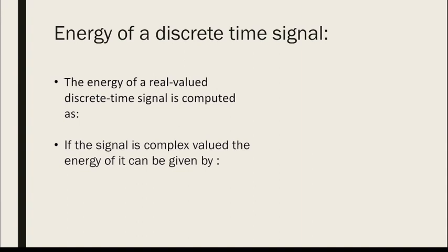Both of these are given by two different equations. For the real value, it's given by Ex equals the summation when n equals negative infinity to infinity of x squared of n, and x of n here refers to the input of the signal.